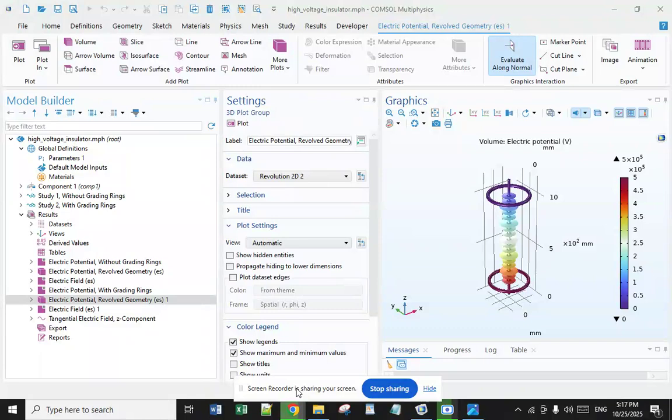Why are high voltage insulators used in electrical power transmission and distribution systems? Actually, high voltage insulators are used to withstand high electrical voltage and hold the electrical conductor in position, preventing current leakage and arcing. What are the most common types of high voltage insulators? The most common types of high voltage insulators are porcelain, glass, silicone, and composite insulators. At points, we recommend ceramic and polymer insulator.